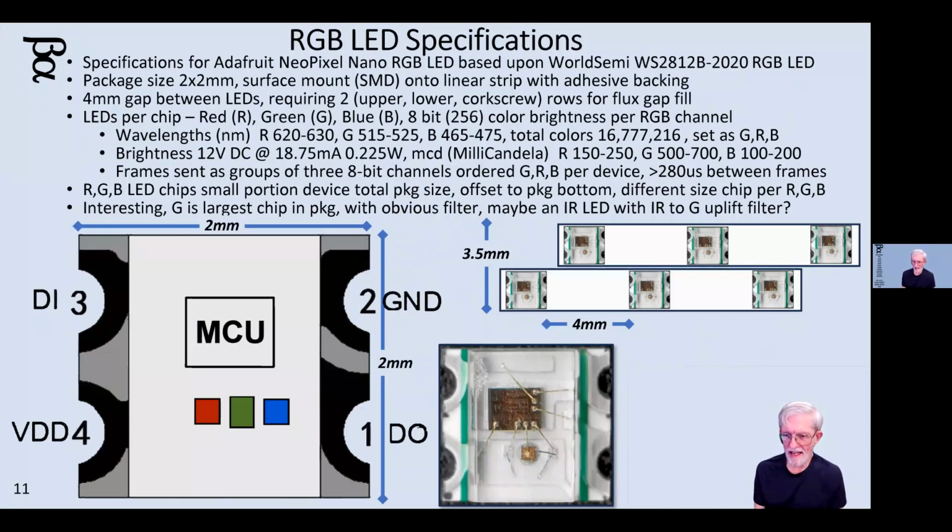And they're just on this strip and they're joined together. So the power just goes from one chip to another. The ground goes from one chip to another. And the serial data signal goes in one chip, out into the next chip's in. So it's out, in, out, in, out, in. And you hook them all together in a strip and you apply power to one end.